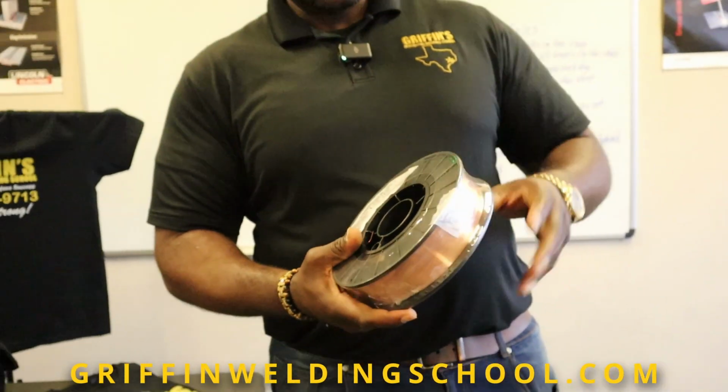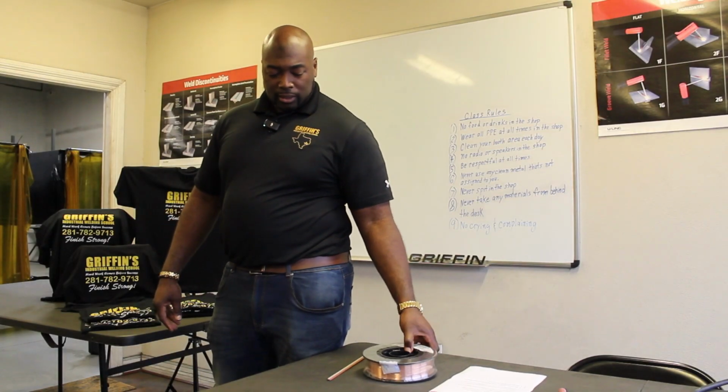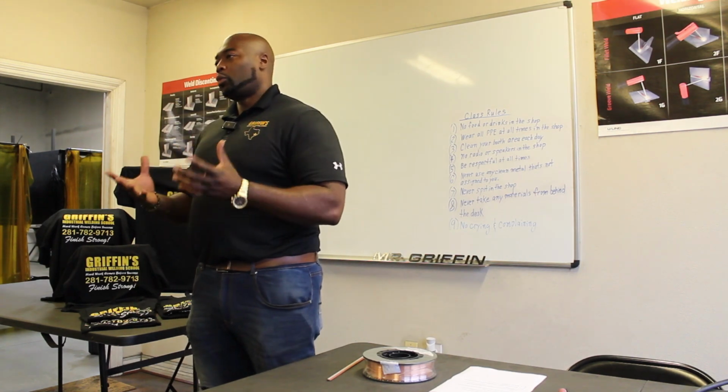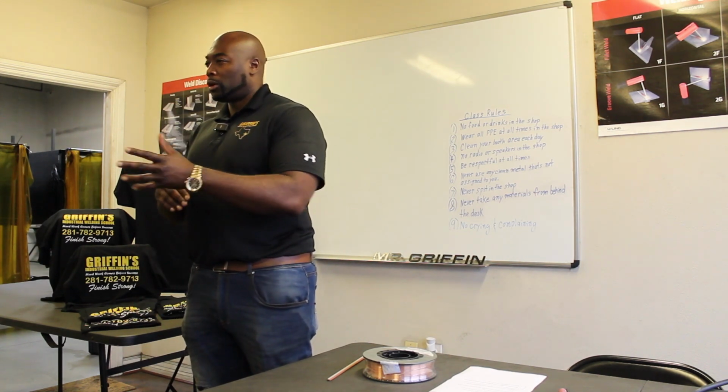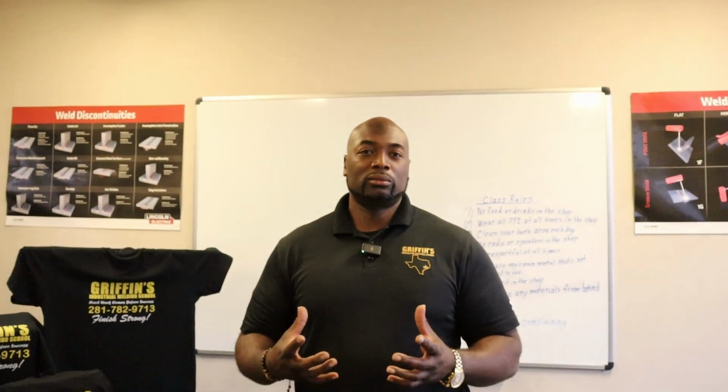When you're doing MIG, it's not quite as durable as stick welding, but it gives you a much prettier weld. So if I'm building a barbecue pit, a table, a chair, or anything that I want to look nice and pretty, I want to go with MIG over stick, because it gives you a real pretty weld, and the heat is not quite as hot unless you really crank it all the way up.